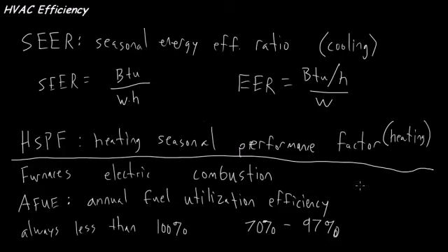And what we mean by that is, for say a gallon of fuel, how many BTUs do you get by burning it. If you know how much heat you're going to need in a season based on the heating loads, you can figure out how much fuel you need if you know the heat of combustion and the efficiency. So that's a good problem to know how to do.